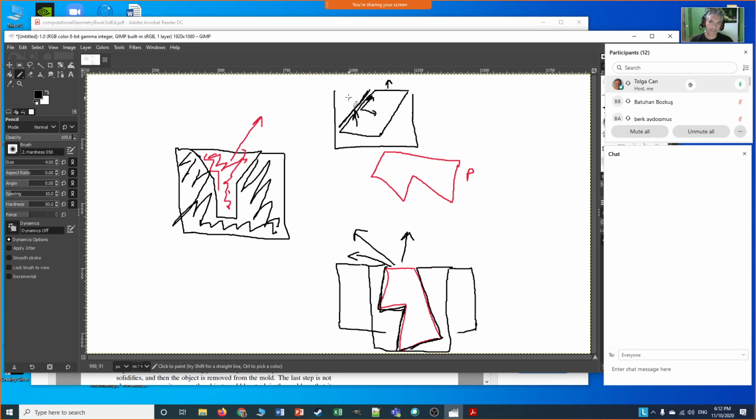What needs to happen is that, whatever the normal of this mold surface is, I can only pull if I have certain angles with respect to that mold face. And in order to pull the plastic safely outside the mold, it has to satisfy this angle constraint for all of the mold faces. I may be going a little bit fast, but I'm going to come to that soon. But you understood the problem, right?